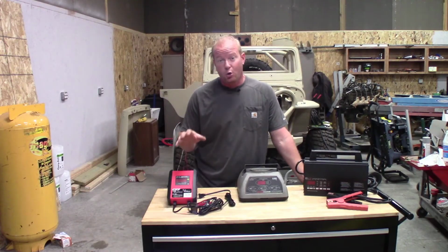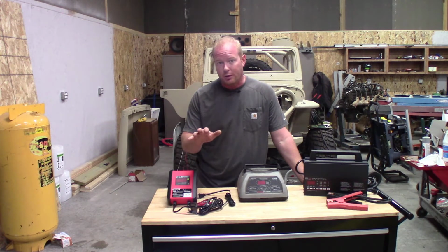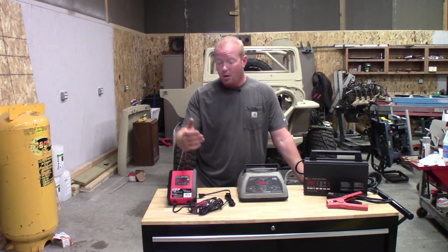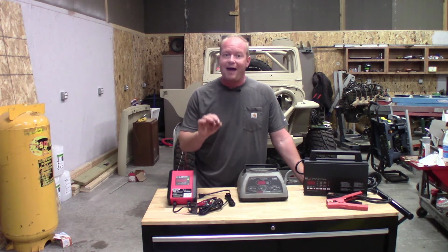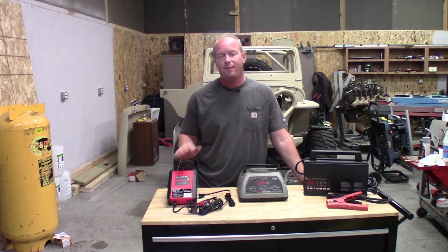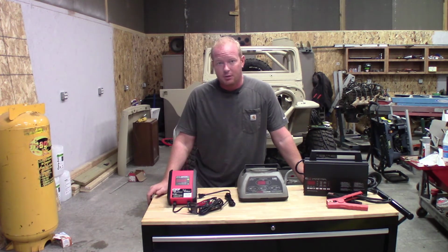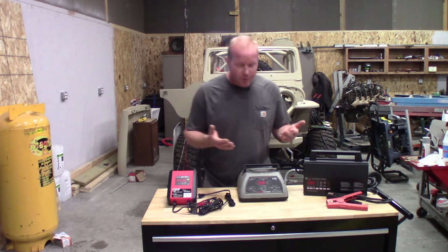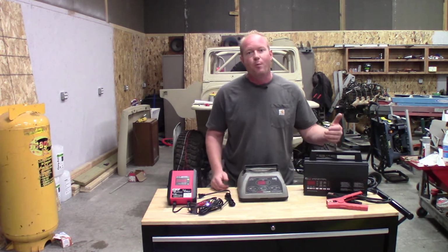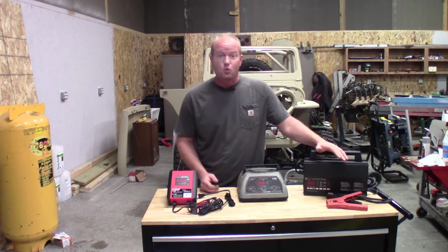When it comes to computer programming, there's one key feature that a lot of people overlook or forget totally, and that is voltage. Whenever we're programming a vehicle via a J2534 box, we have to make sure that we maintain the proper voltage in that vehicle throughout the entire programming session. We're going to go through the difference between a battery maintainer, a battery charger, and a stable power supply, how they work, and what the difference is in each one.